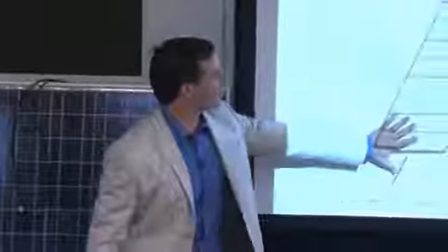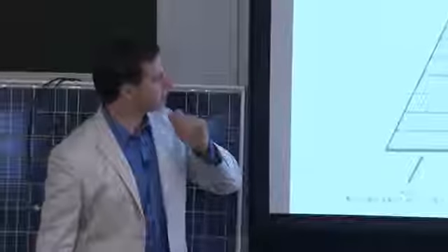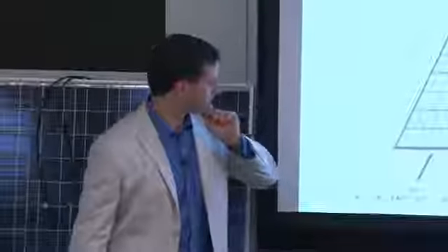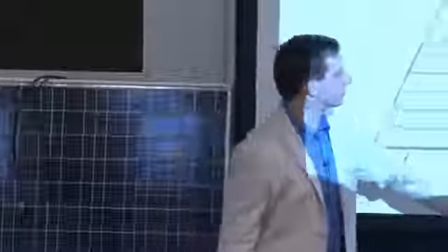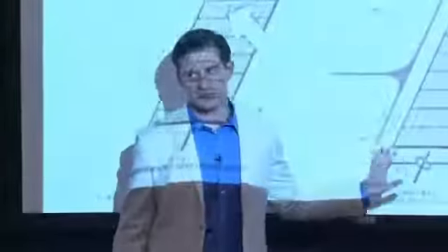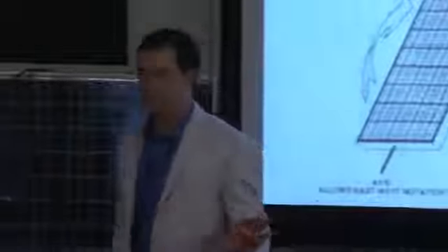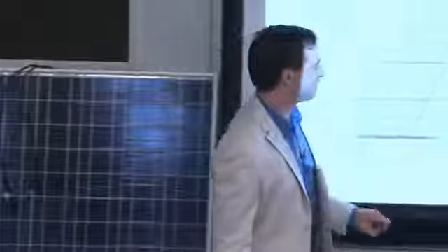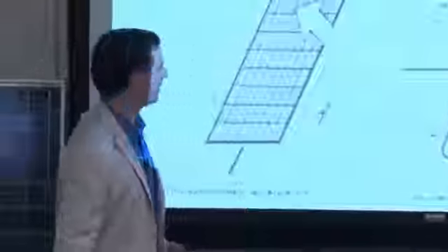The reason one-axis tracking is taking off as, say, the most common field installation tracking system is because the seasonal adjustment, if it really needs to be done, it's not a huge energy benefit, but if it really needs to be done, you can probably just crank it by hand instead of using a machine or a motor that can break down. And the adjustments don't need to be made very often.